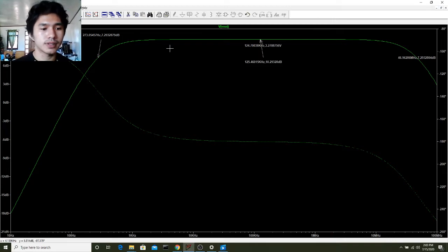But the formula for the gain in decibel will be slightly different since you'll have to use the formula 20 log times V out over V in, and it resulted to a V out of 10.29328 over 20 millivolts. Then I multiplied it to 20 log, which resulted to a gain in dB of 96.